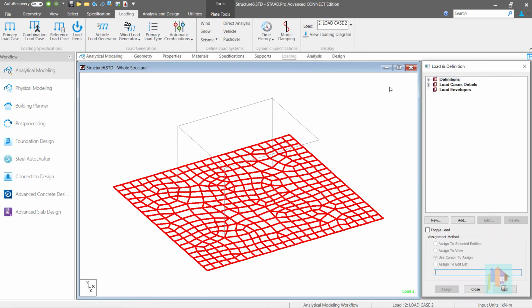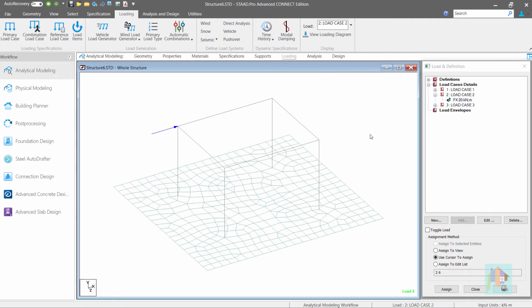Load 2 is a purely lateral load. A load from x direction is applied on the structure. And that's it. Weight of the structure is also not considered. When program analyze for this load case, a weightless structure with no gravity load is considered, which is subjected to some lateral load. So there must be some lateral movement. But this is not the real case.